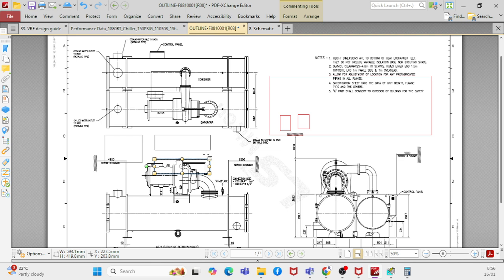Yes, this is for air cooled chillers, typically 3 meters. Whenever you discharge heat from the condenser, the same air should not come again as an inlet of the condenser. That is why they keep the distance between two chillers, and they also give space below the chiller so that there will be proper air circulation. So an air cooled chiller consumes a lot of space.